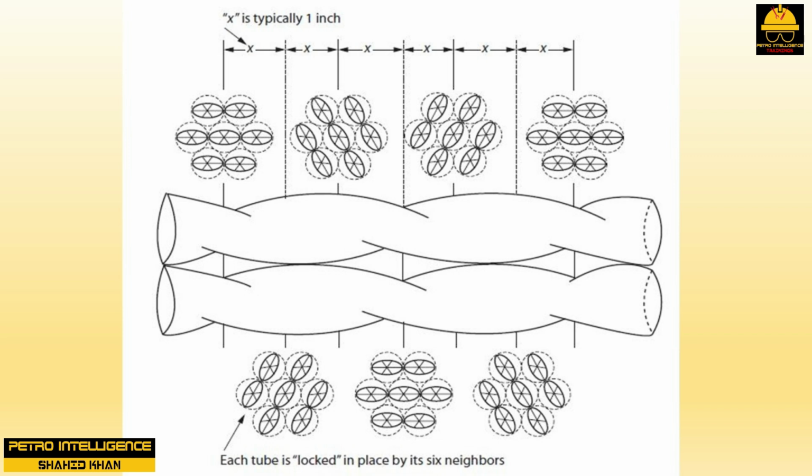One might think that to have the tubes touching would cause a problem with shell-side fouling, but the manufacturers claim that because the points of contact occur on the curved ridges of the tubes, rather than being a problem, the points of contact actually increase shell-side turbulence. The manufacturers also claim that because of all these points of contact, they are able to avoid the use of baffles for tube support and therefore eliminate problems of vibration.